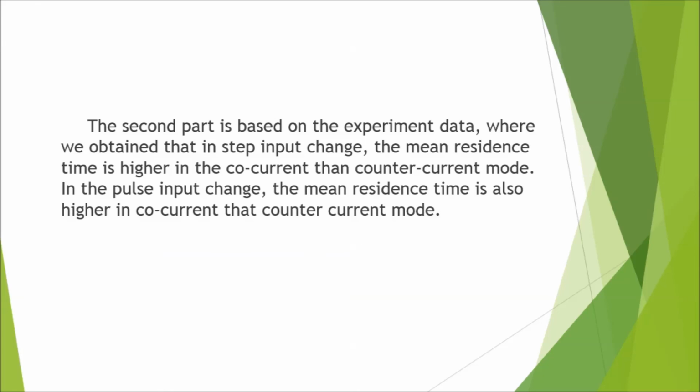The second part is based on the experiment data, where we obtained that in the step input change, the mean residence time is higher in the co-current than in the counter current mode. In the pulse input change, the mean residence time is also higher in co-current than in counter current mode.